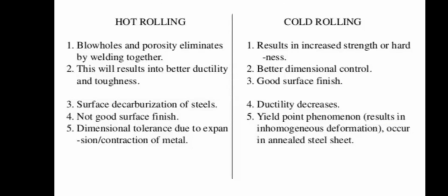In hot rolling, any blowholes and porosity will be eliminated by welding together because of compressive force. The welding of the blowholes and porosity takes place.